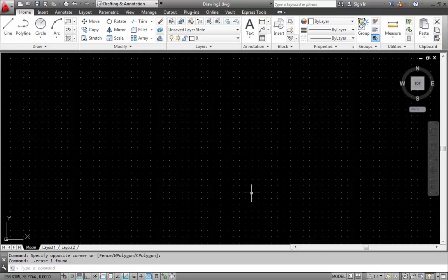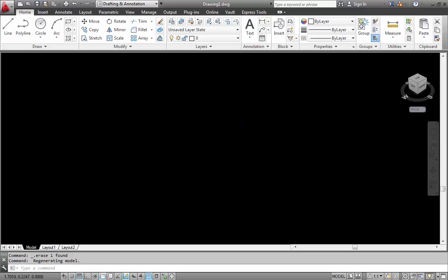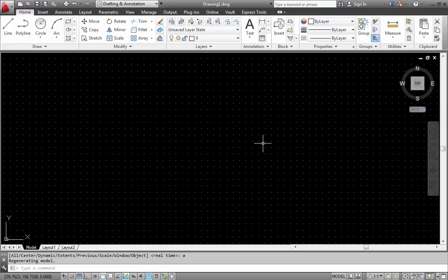A couple of the newer things on the programs over here, you will have what's called a view cube, and that will change a view from a top view to a side view. Don't use this for what we are going to be doing, but if something happens, for example, you hit the home button by accident, you can see how this is turned to a 3D with an XYZ. What we can do is just come back up to here and click on top. You can see it goes back to the top view. And again, I'm just going to type in zoom and then A for all,